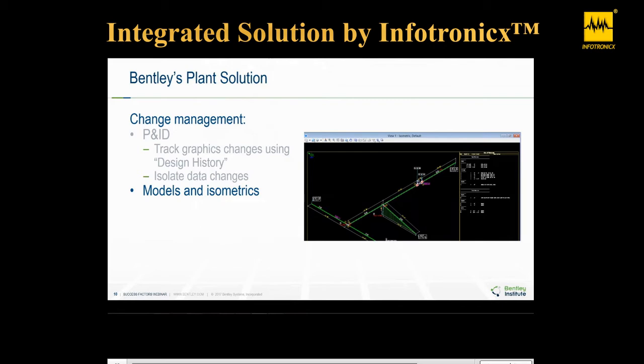So one of the other big advantages of 3D modeling of piping is the automatic creation of isometrics used for fabrication and assembly. In fact, owners are known to maintain the isometric as part of their plant records. So Bentley's isometric drawings are a little bit different in that they are intelligent and contain all of the design properties for fittings, piping, and nozzles, etc., that are used in the 3D model. Those are embedded into the isometric drawing as well. And this provides an ideal reference for inspectors and maintenance crews.